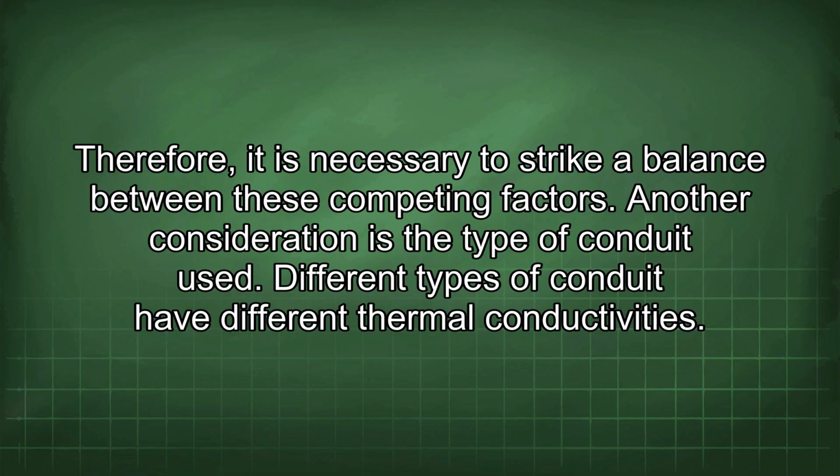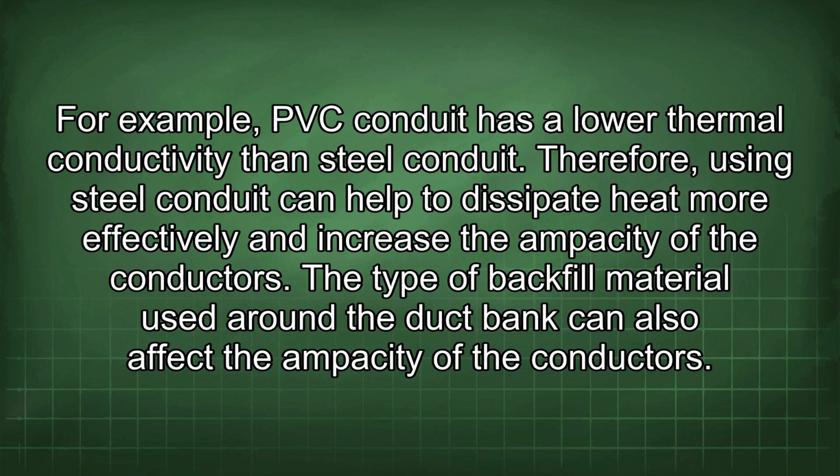Another consideration is the type of conduit used. Different types of conduit have different thermal conductivities. For example, PVC conduit has a lower thermal conductivity than steel conduit. Therefore, using steel conduit can help to dissipate heat more effectively and increase the ampacity of the conductors.